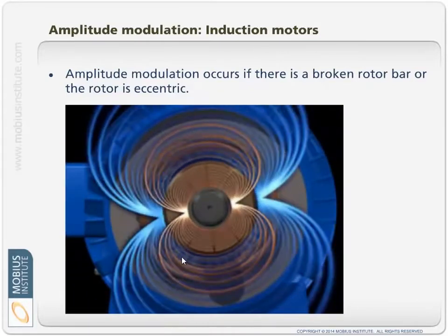What we find is that the ripple of vibration due to that, when it's right in the center of this strong magnetic field, the forces are greater than when it happens to be at this point. So because of the slip frequency, as the broken rotor bar is in the magnetic field versus outside the magnetic field, in the strongest part and in the weakest part, we get this rise and fall in vibration. That's the pole pass frequency. It's the slip times the number of poles.